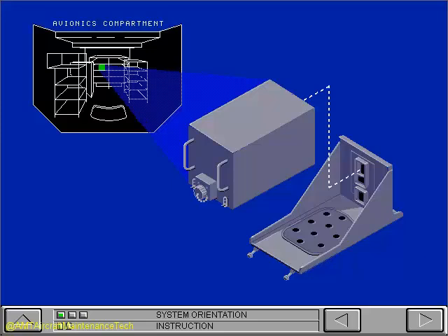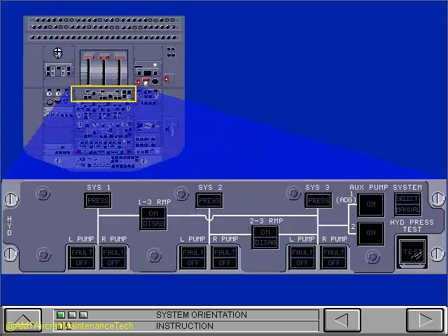The hydraulic system controller, or HSC, controls the hydraulic system through 2 modes of operation, manual and automatic. In the manual mode, the hydraulic system control panel, or HSCP, controls, monitors, and if necessary, resets the system and components for any aircraft failure. The HSC is on the main avionics rack in the avionics compartment. Switch lights that give commands to hydraulic system components are on the HSCP.